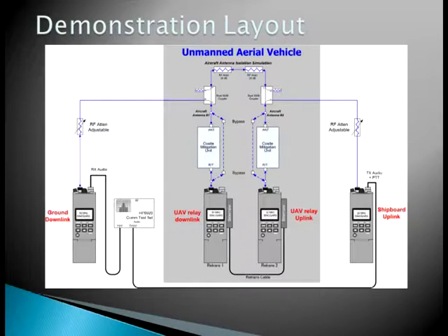On the right half of the drawing is the relay uplink with the corresponding downlink on the left half of the drawing. The only coupling between the two links is the retransmission cable coupling the audio signal from the uplink to the downlink to perform the relay function, and the RF coupling at the top of the chart, which simulates the 40 dB isolation assumed between the downlink transmit antenna and the uplink receive antenna. The following video will show the actual hardware used in this demonstration.